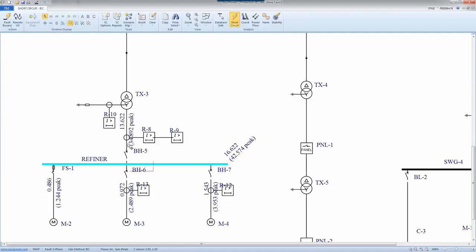If you have only one branch for method C, you would see that the peak value would be equivalent to the peak value coming from method B most of the cases, and in fact it would be as if you don't even apply any 0.4 factor. That 0.4 factor, which looks like you're doing and undoing something, is effective if you have a combination of more than one branch.